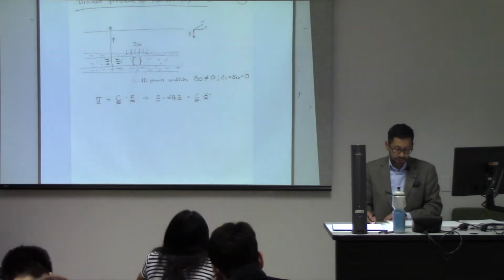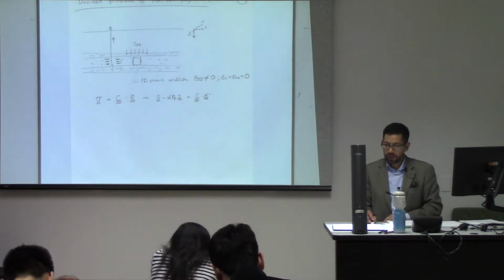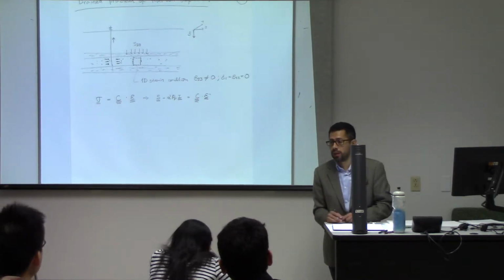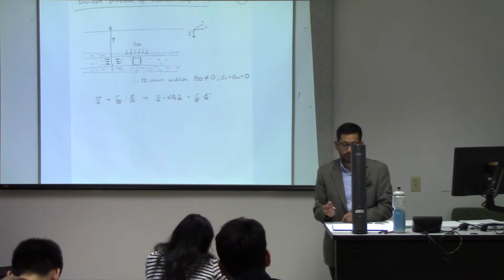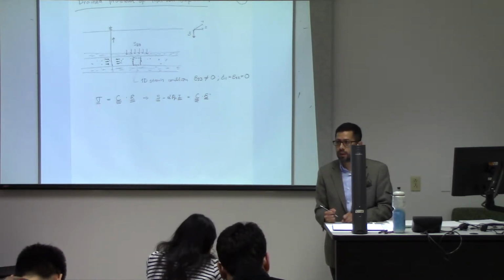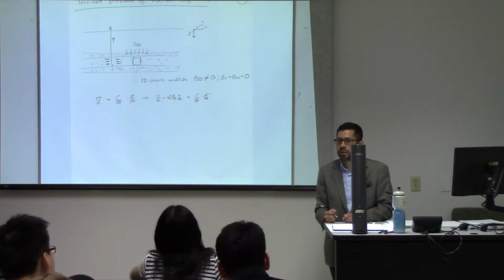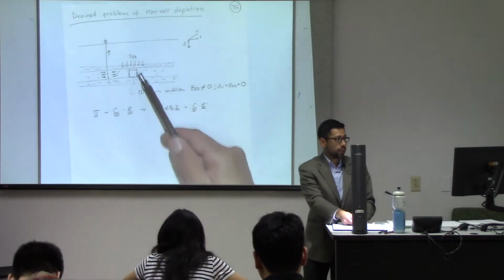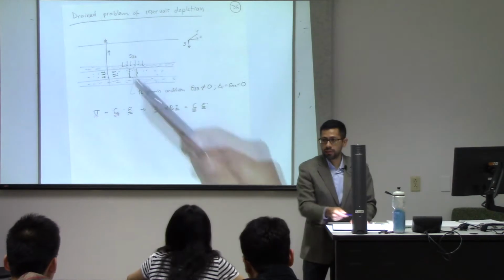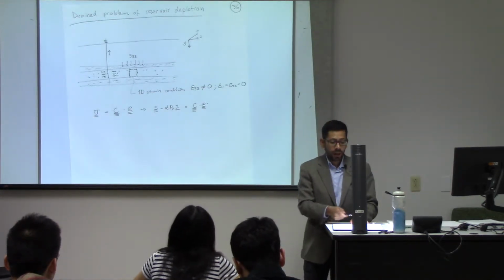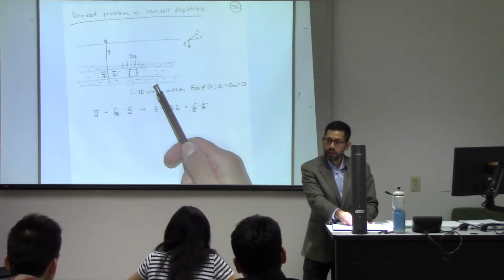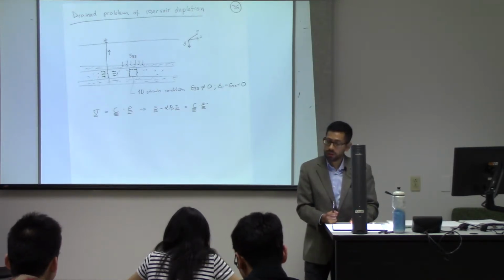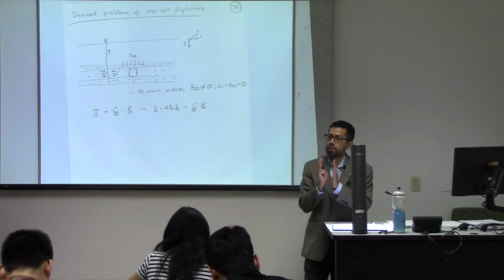And in this case, we're going to work with total stresses. You may say, why are we working in total stresses if effective stress is what is really making the rock deform? The problem in this case is it's very difficult, almost impossible to measure effective stresses in situ. You cannot measure that. You can measure total stresses. For example, if you wanted to predict overburden here, it would be the weight of everything on top. That's going to be the total stress. And if you wanted to measure horizontal stress in here, you would have to do a hydraulic fracture test. And a hydraulic fracture test is not going to measure effective stress, but it's going to measure total stress.